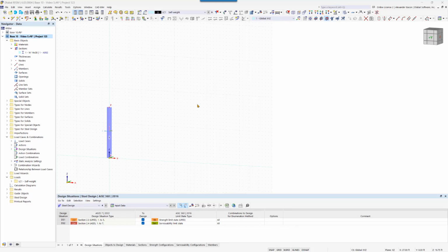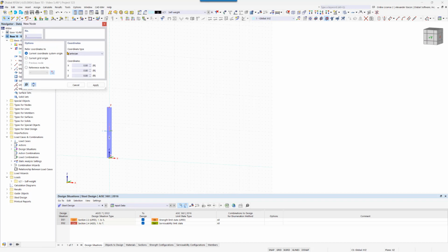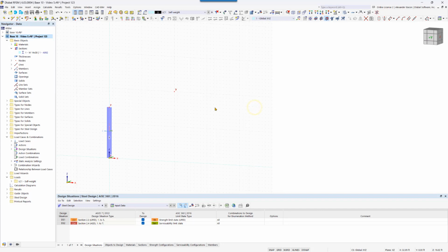In this video, we continue modeling our steel hull by creating the first two-dimensional frame. Let's start immediately and insert the top node of the dual pitch roof. We click on the new node icon and enter the desired coordinates, and then confirm the entry, which we can do by hitting enter. Now we can right-click to cancel out of that tool.